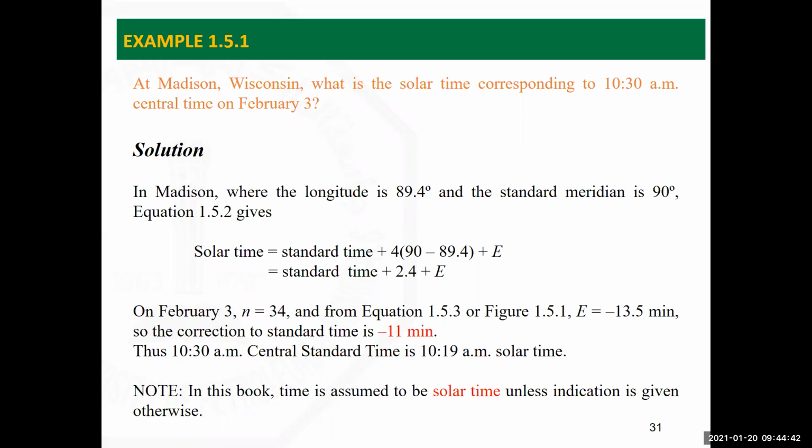The standard value is the one given for Riyadh, the standard of the kingdom. And the local value is the local longitude in Dhahran. Then you substitute in this and calculate the solar time. Then take that solar time to calculate the hour angle after this.